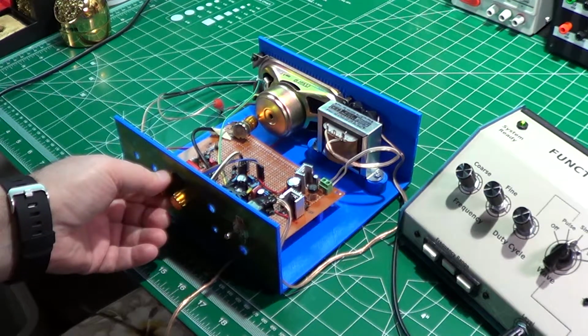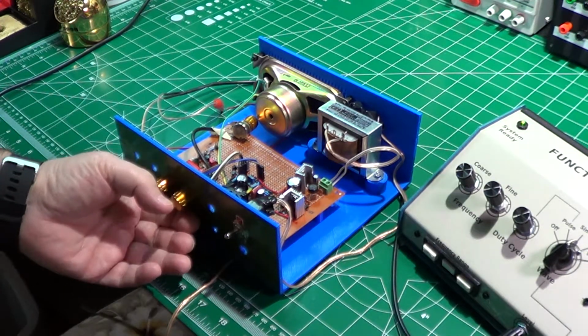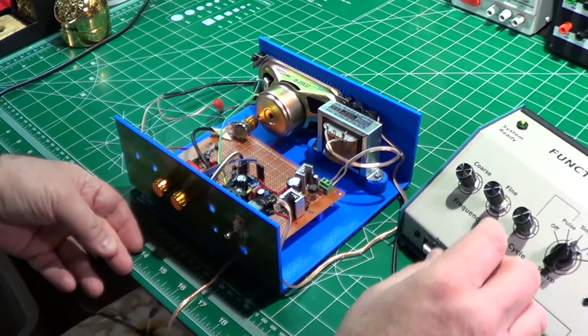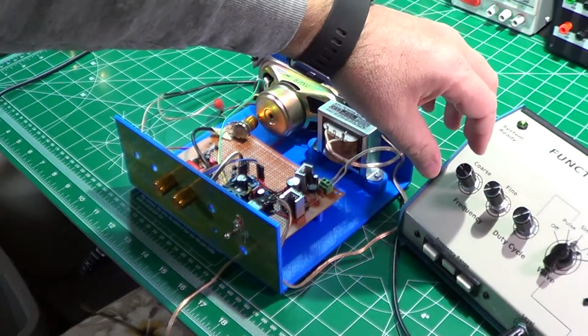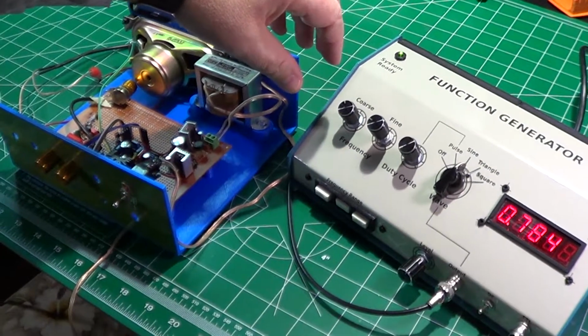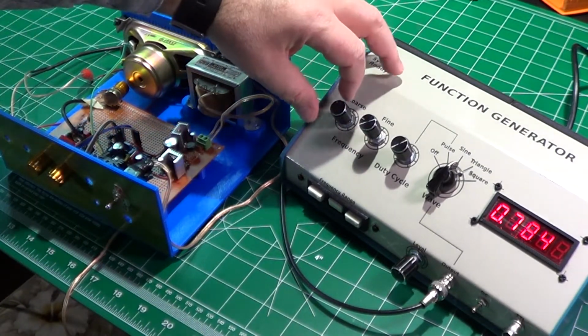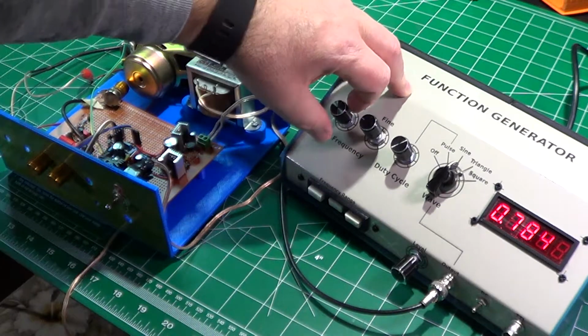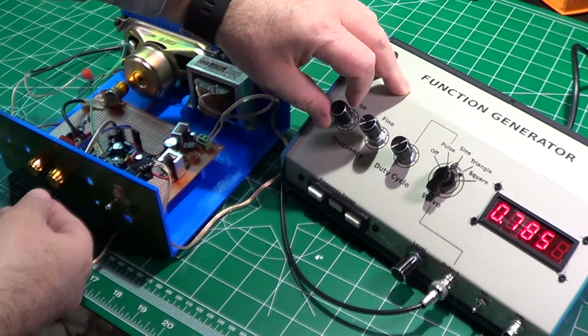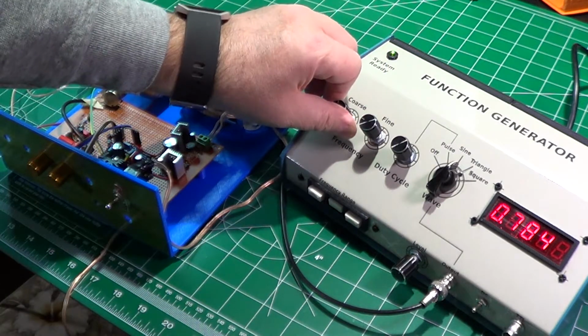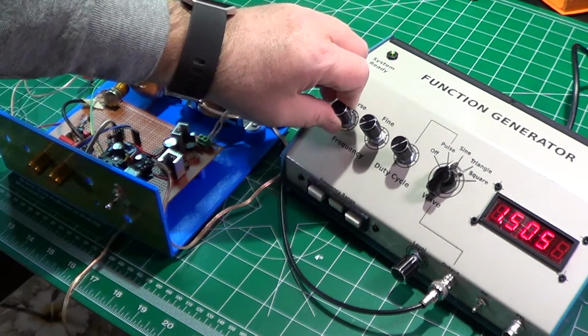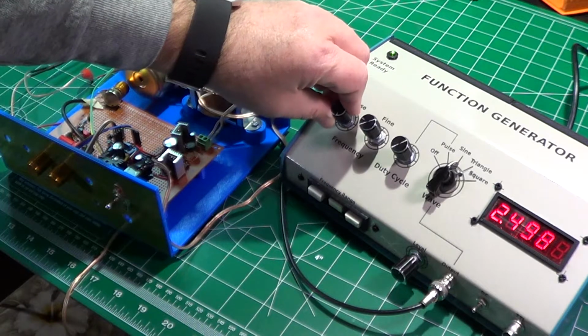To check the brightness control, I set the brightness potentiometer to a certain position and hear how the audio signal sounds at various frequencies. Then I change the potentiometer to a different position and hear if there is any change in the sound response at the various frequencies. We do want to hear changes happening. If so, it means that the brightness filter is doing its job.